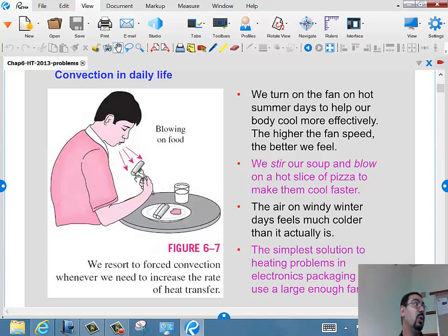The whole idea behind convection is that you are not happy with that rate of heat transfer. The next layer of air sticking to the pipe or the tank or the wall is probably going to get very hot very soon, and therefore there will not be much temperature difference between the hot air and the hot wall. And so the air will not suck that much heat out of the wall.